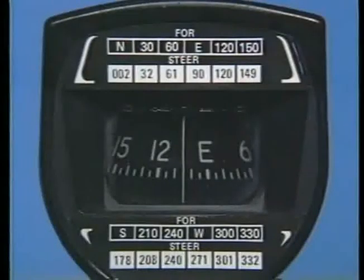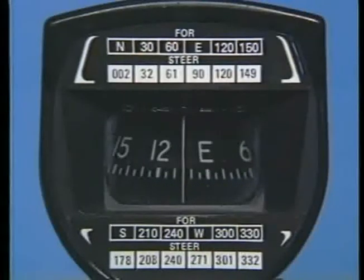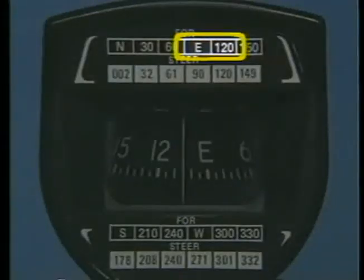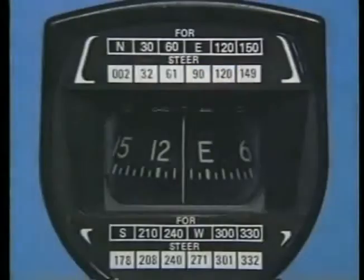Now you are ready to adjust the magnetic heading for deviation by compensating for the instrument and installation errors in the magnetic compass. This card tells you what heading you should steer for a particular magnetic heading. The magnetic heading for this flight, 105 degrees, falls between east and 120 degrees. Since neither of these headings requires a correction, the compass heading will be the same as the magnetic heading.